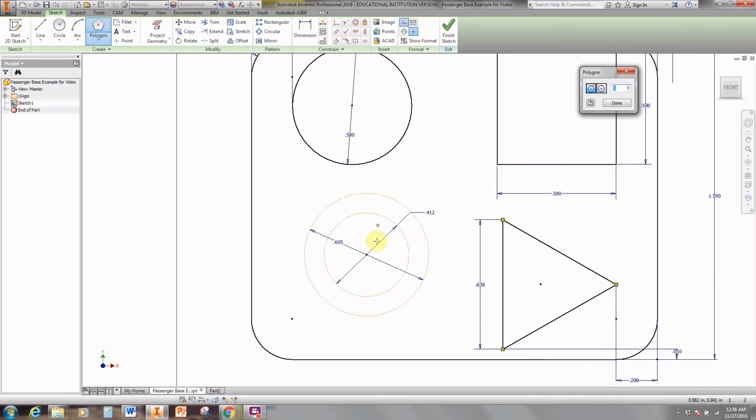Also, construction. We're going to click, and we want to make sure that it's 5-sided. Pentagons are always 5-sided. We're going to get a green dot right there, smack dab in the center, concentric. And this is going to be inscribed between our two circles. It's going to be an inscribed pentagon.